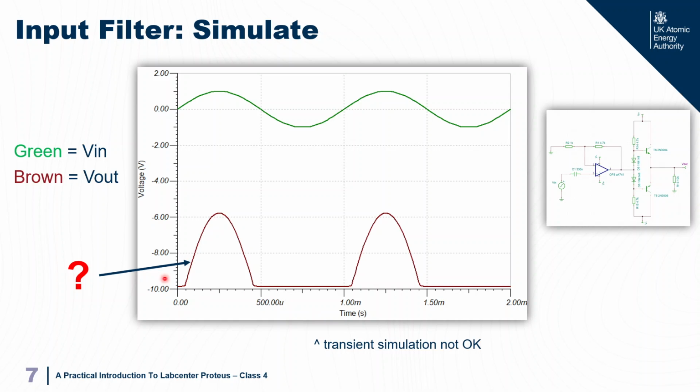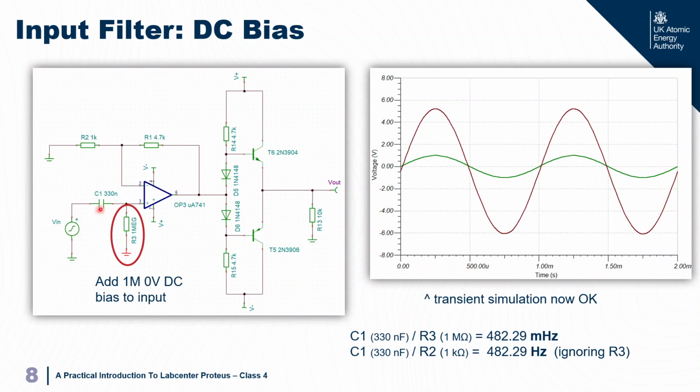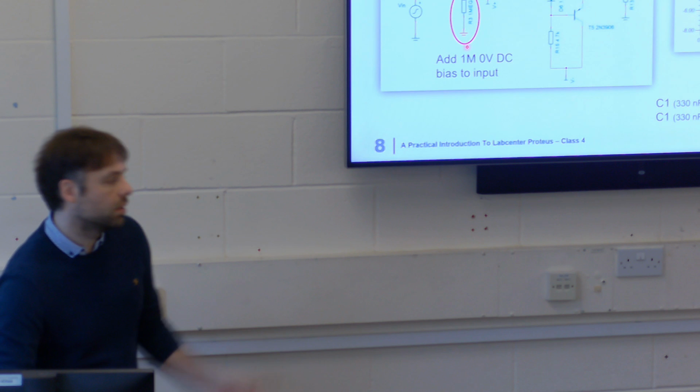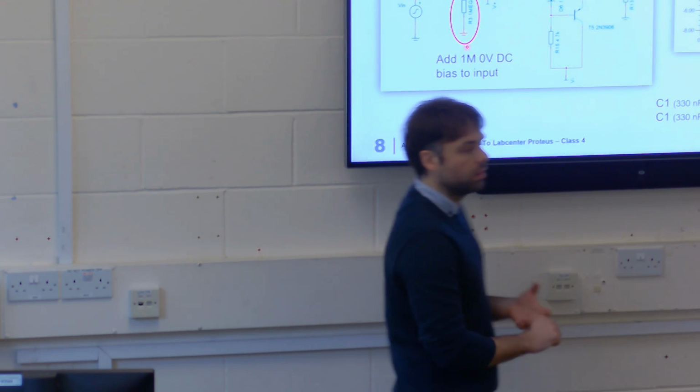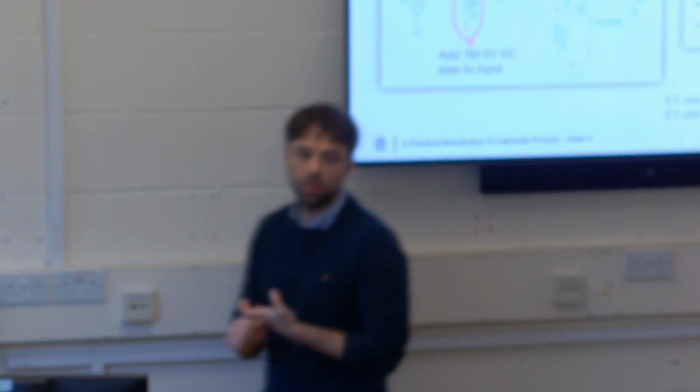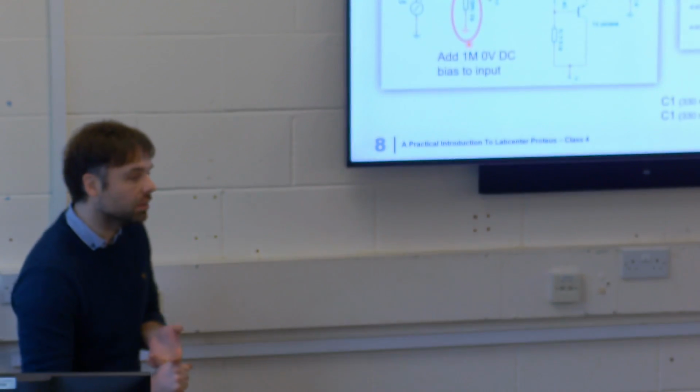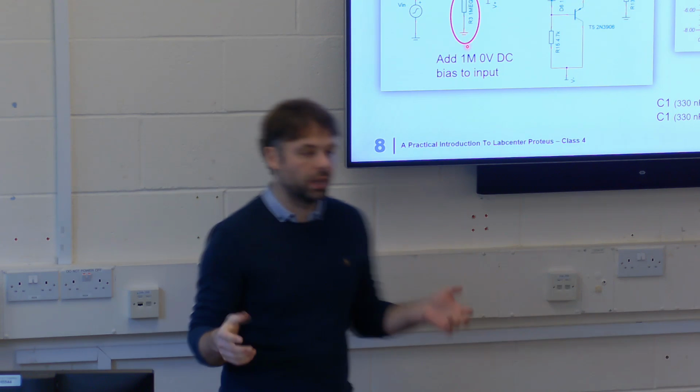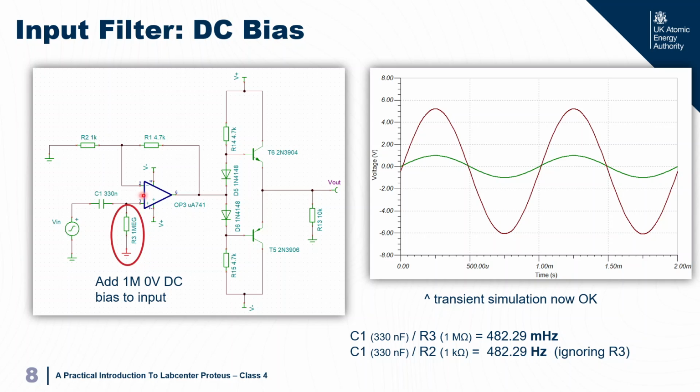So what's happened is the output has hit a rail against minus 10 volts. That would absolutely not work. The reason for that is because this input pin had no reference to ground. There's no bias. So in reality, even though one of the two rules of an op-amp is that it takes no input current whatsoever, that actually isn't true. Nothing's perfect. As this pin is drawing a fraction of a little bit of current, that will create an offset with that capacitor.